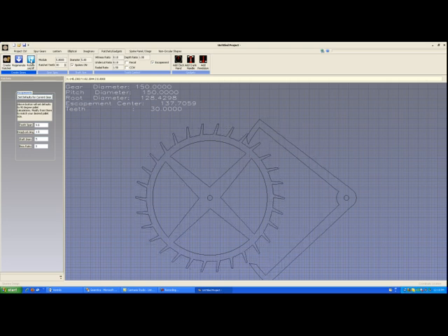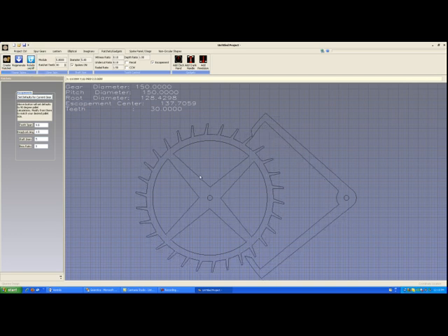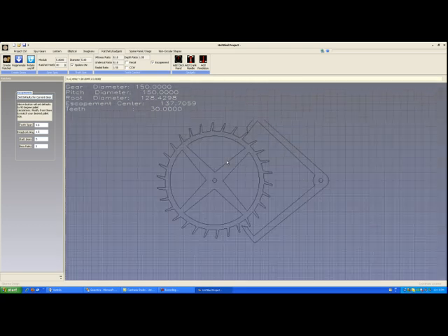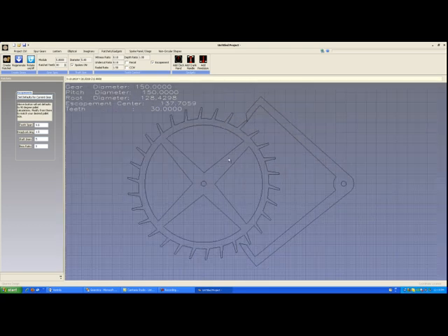And when the tooth goes to push on the impulse pallet to add energy to the pendulum, we now have a much longer time of energy transfer. So you're going to find that the defaults are actually pretty good for making a fairly high quality escapement in terms of energy transfer.